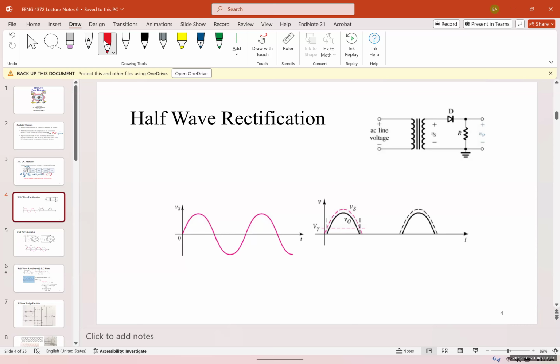They have low and high. For example, if I connect this part, it's going to be the high. If I connect the second part, it's going to be the low. And what a half-wave rectifier does, as its name states, is cut the lower half of the signal, and you're going to be left with only the positive side. Obviously, we have a diode.